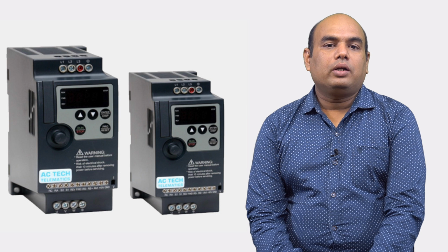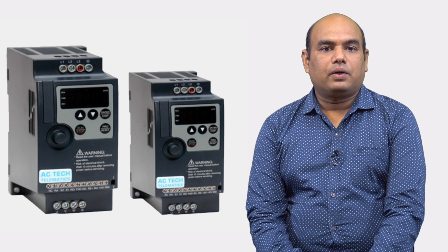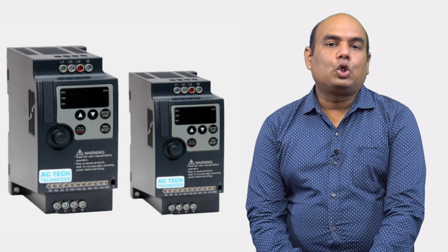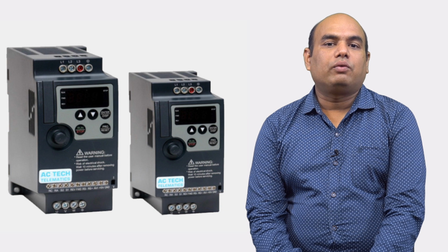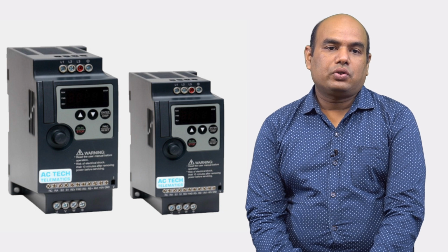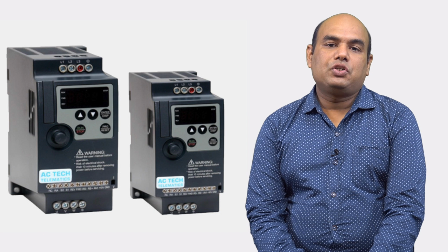These are called square wave or variable voltage inverters. If the voltage control is available in the inverter itself, the input voltage of the inverter is constant and a simple diode rectifier is sufficient on the line side.